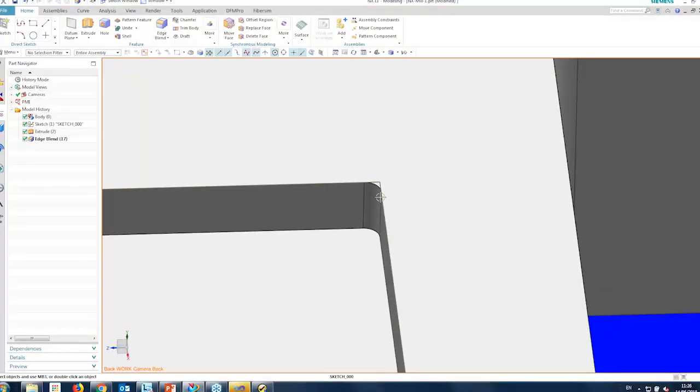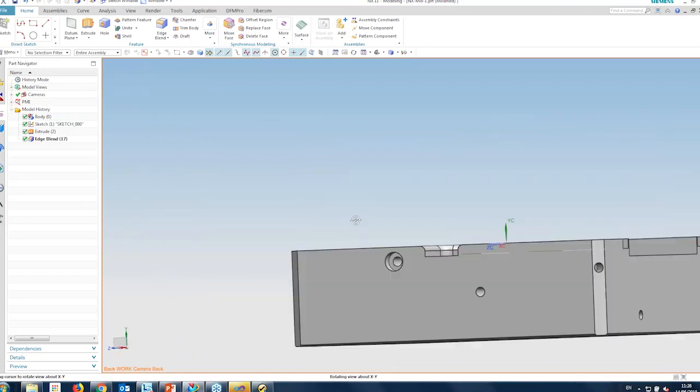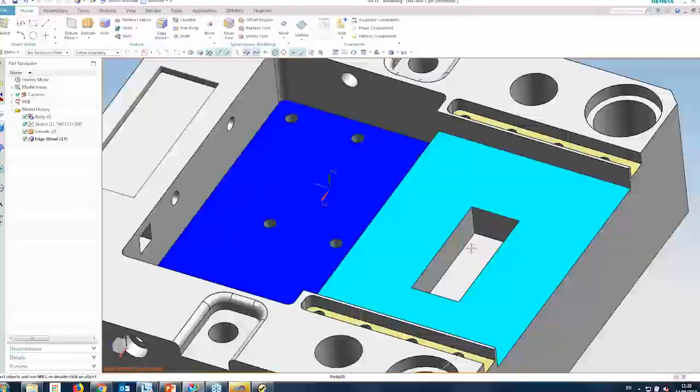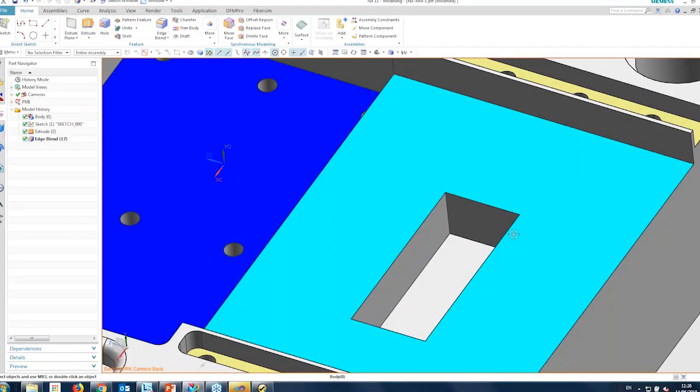And then I click on the individual instances. I click on that specific area. It's showing me that in this particular direction, I have sharp internal corners in this particular pocket. And it's giving me the same message here that sharp corners are present, so avoid sharp corners. Similarly, if I look at the other instance here, I have some sharp corners at this particular area as well.